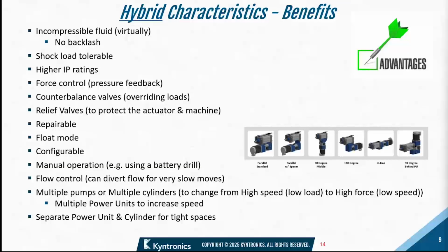Force control, I mentioned. The counterbalance valve is a nice little feature that helps in a more cost-effective solution. So it can lock, and it can help with controlling things like overriding loads and those sorts of characteristics. Relief valves protect the actuator and machine. As I mentioned, they are repairable solutions. Float mode is a nice little feature. You can share the fluid from both sides of the piston, so you can move the rod back and forth very easily.